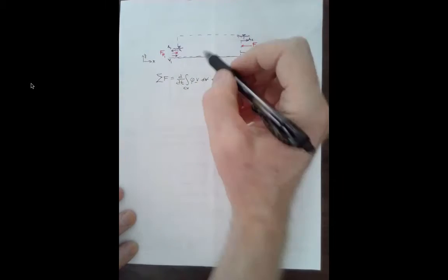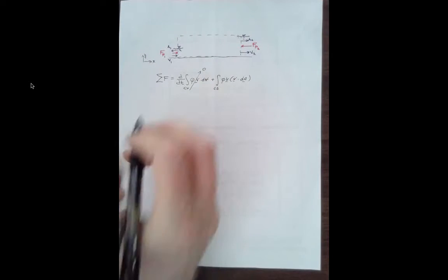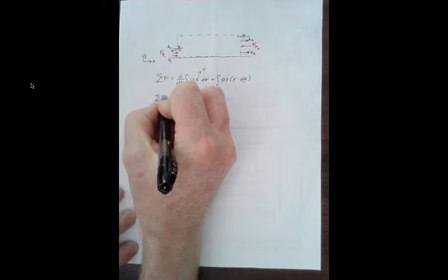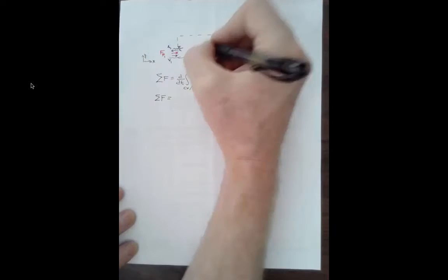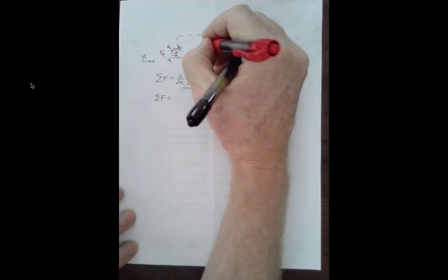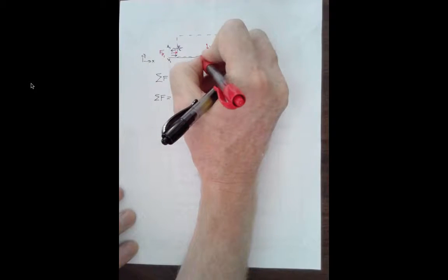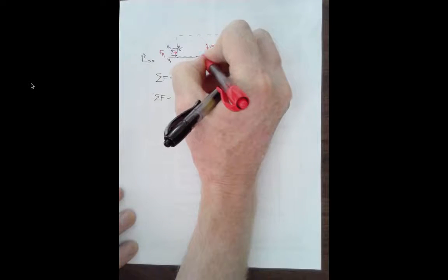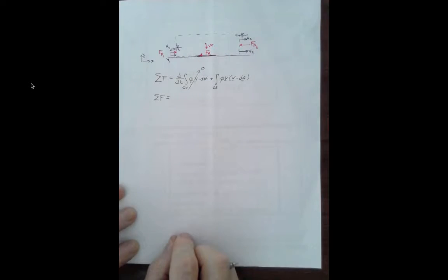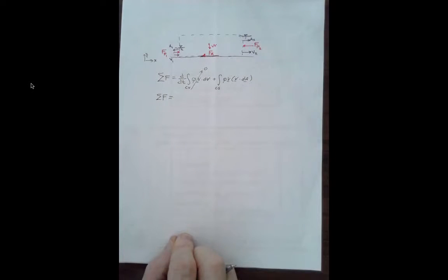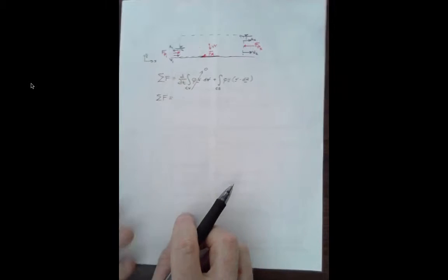The way I've drawn it, my control volume is not deforming, so that part zeroes out. And so finally we have the sum of the forces, and we'll put the left pressure force, the right pressure force. There's the weight force, and we would certainly have friction. I may choose to eliminate friction or to neglect it because this distance is short. The frictional shear isn't going to be terribly huge.